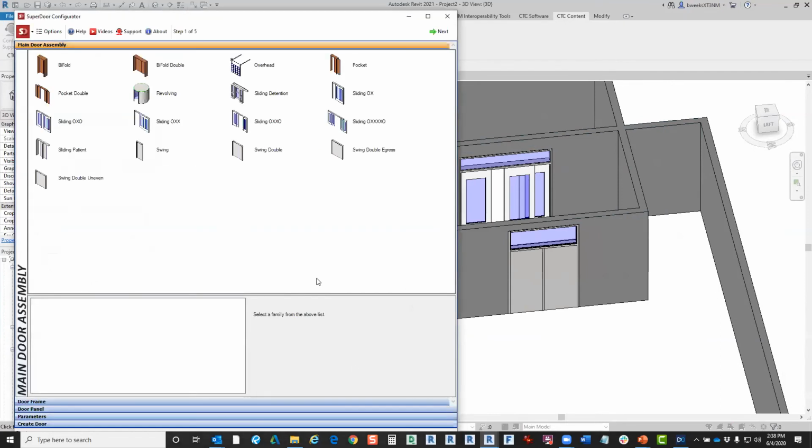Now the individual profile itself, such as a sweep, or something like an OG profile or a semicircle or even an angle. Some of that detail really is not intended for Revit per se, because when you get down to that small a detail, a lot of times that detail does bog down your model.